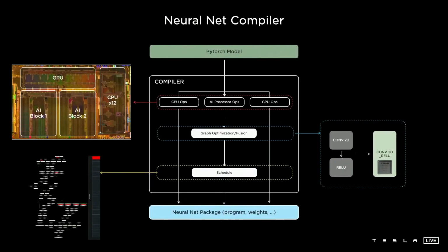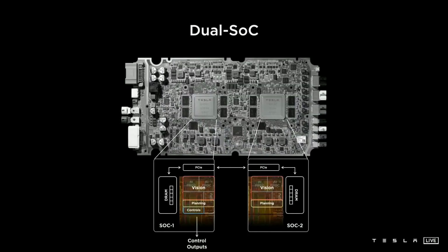And so the meat of the problem really is around the AI compiler that we write and extend here within the group, that essentially maps the compute operations for my PyTorch model to a set of dedicated and accelerated pieces of hardware. And we do that while figuring out a schedule that's optimized for throughput while working under severe SRAM constraints. And by the way, we're not doing that just on one engine, but across two engines on